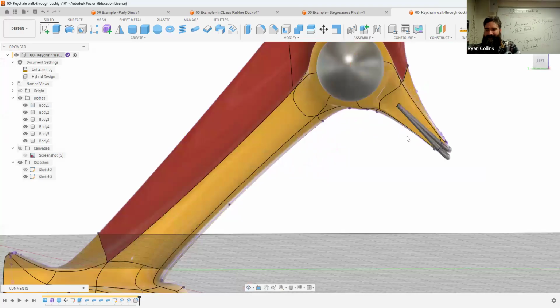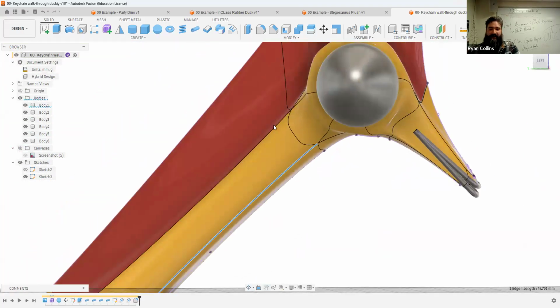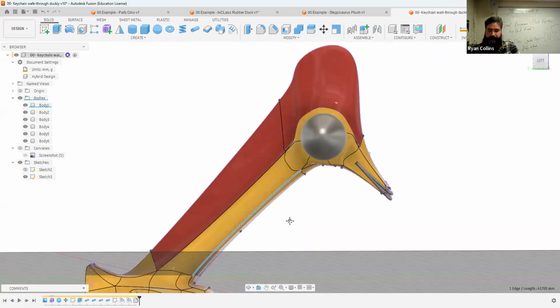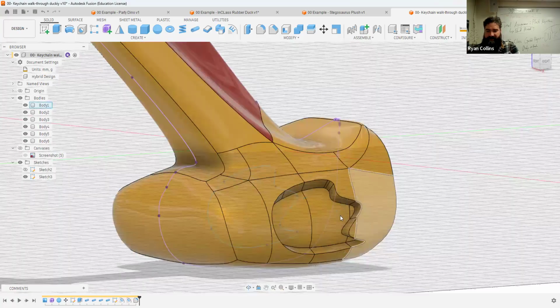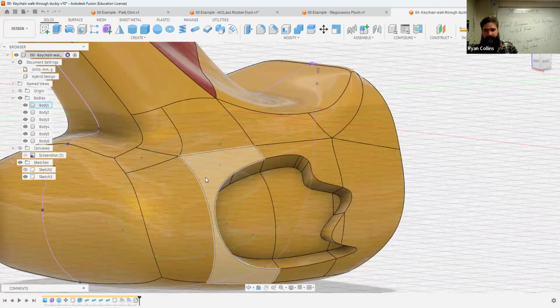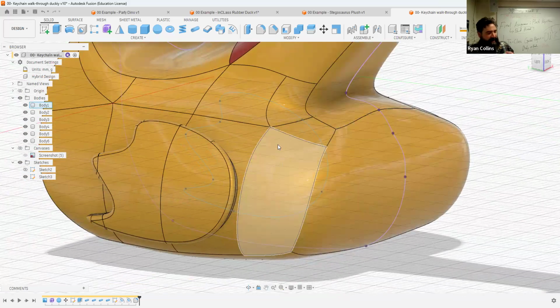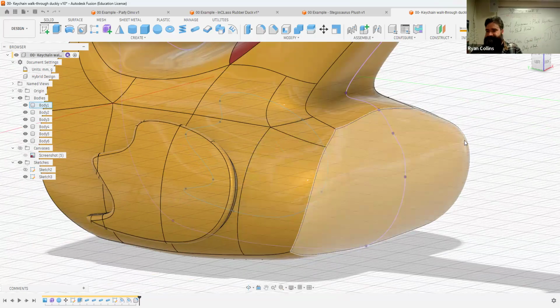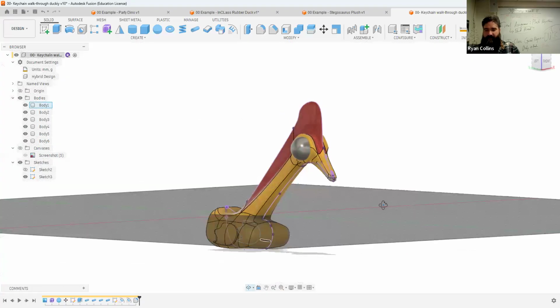So that's a really simple way of adding additional features onto the surface: either sketch and extrude to cut inward, a pipe tool to actually make use of the edges that are created from this line, and sketch and emboss to either deboss, which is pushing inward, or emboss, which is going outward. The reason this works is the sketch is smack in the middle, so it can affect either side of the object. So those are a few of the ways to make your own nightmare fuel.